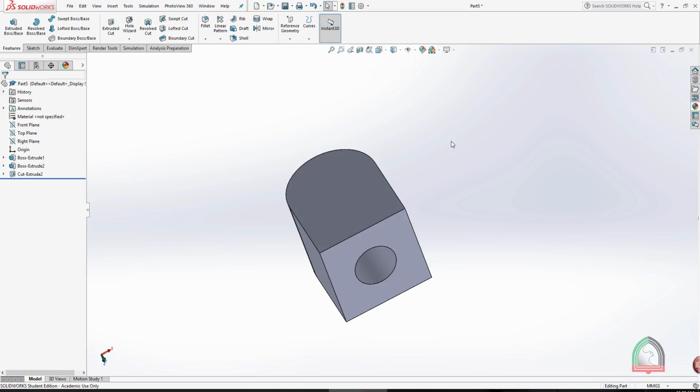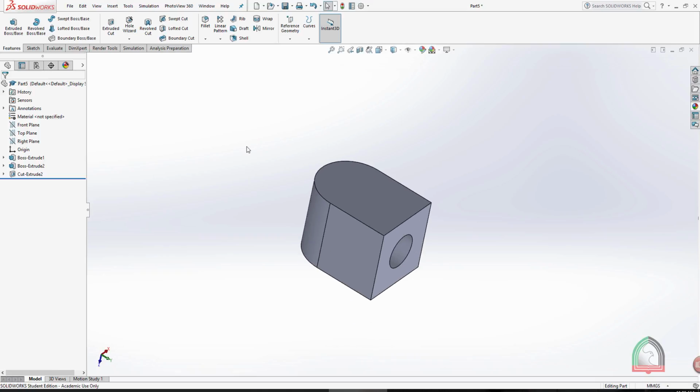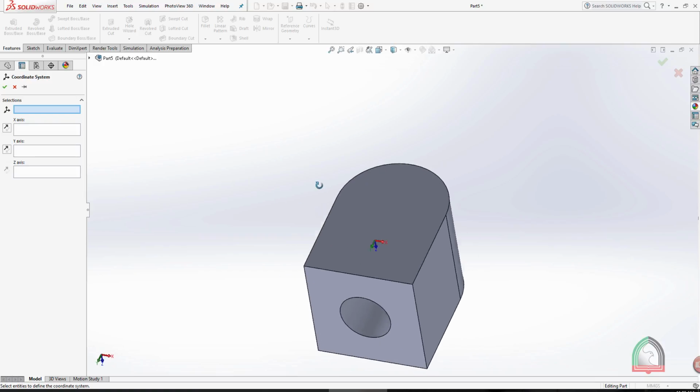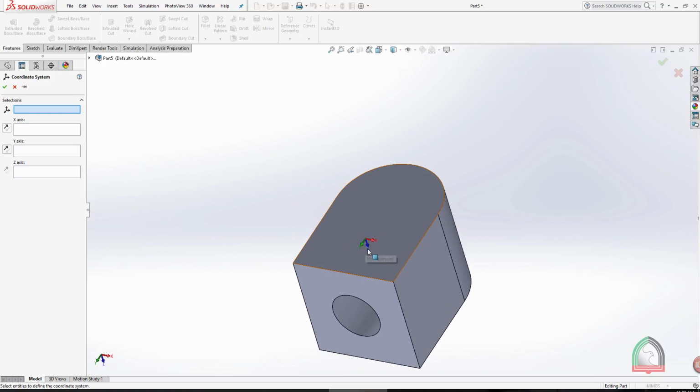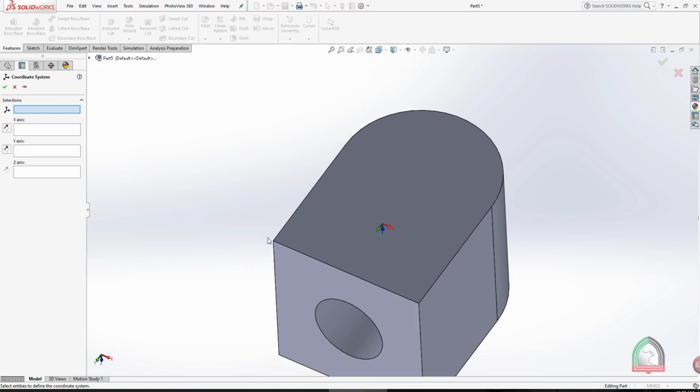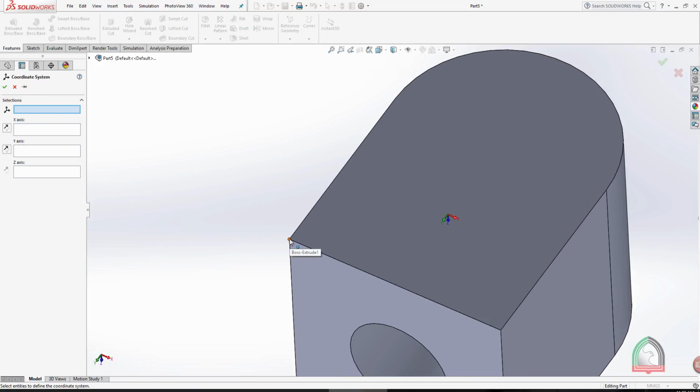As I mentioned earlier, at the beginning of drawing you can see that we have a coordinate system over here. We are taking that coordinate system as the reference. If you want to make a separate coordinate system with the x, y and z, we can use this one. Here it will ask for a point. This is our geometry coordinate system provided by the software itself. I want a coordinate system here in this point. The meaning is I want to make this point as my x0, y0, z0.